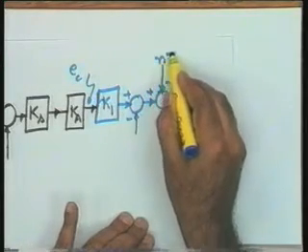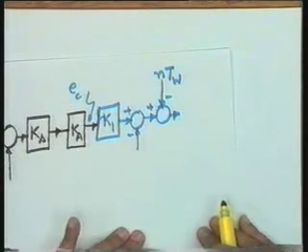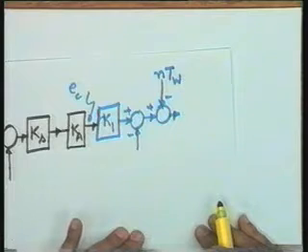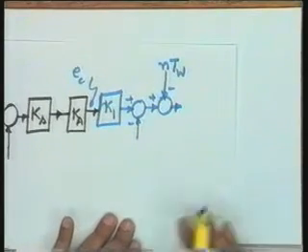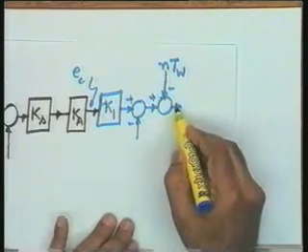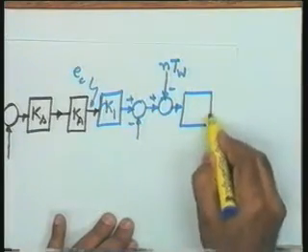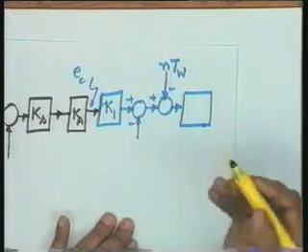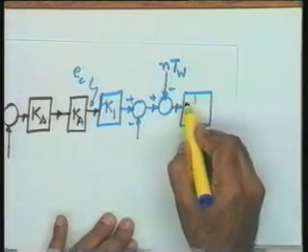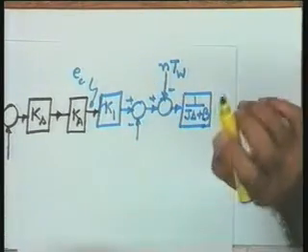NTW. Please see, it is NTW because the disturbance reflected on the motor is NTW, where N is the gear ratio. TW is not directly acting on the motor now. It is through the gear set, and therefore the disturbance is NTW. So this is the net torque available to drive the load, and the load parameters of the camera are JL and BL. Let me say, when they are reflected onto the motor, they become J and B, therefore I am writing 1 over JS plus B.